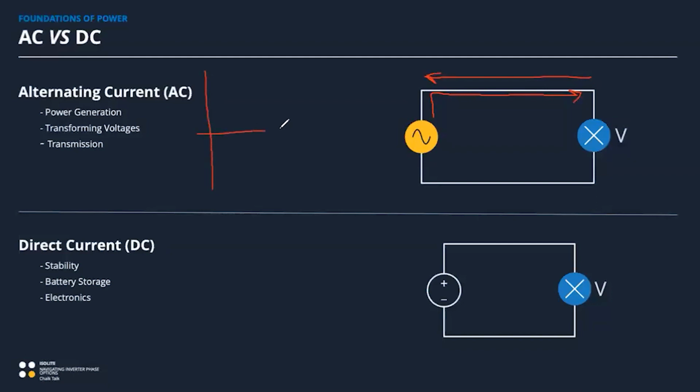This is where we actually get that sine wave that we tend to think of when we think about the power systems that we're dealing with, right? This side right here means that current's flowing in the positive direction. This side means that current is flowing in the negative direction. And for those of you who did your pre-reading, you would know that this is a 60 hertz signal, which we'll talk about. So this happens 60 times every second in power systems, really like the power generation systems.